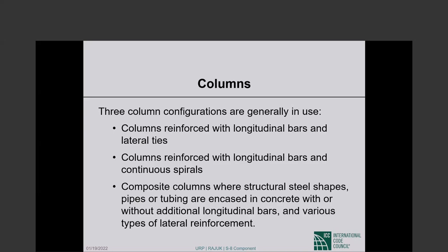Now, the spirals typically, not necessarily always, but typically are used in circular columns. Circular columns are fairly common in bridges. The bridge piers supporting the bridge deck are quite often circular, but in buildings, circular columns are, I would say, increasingly uncommon. I do not know definitively anyway what the reason is.